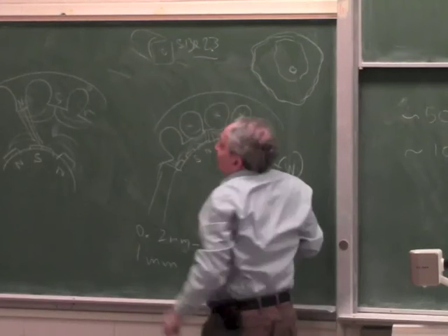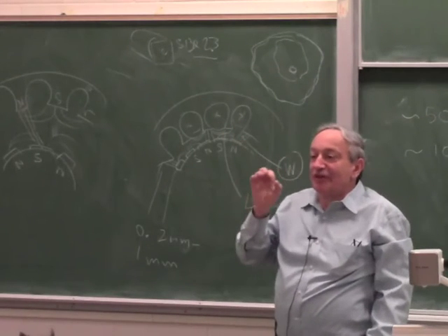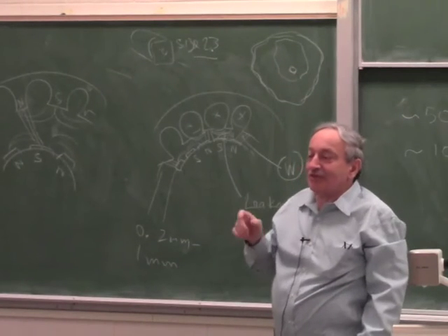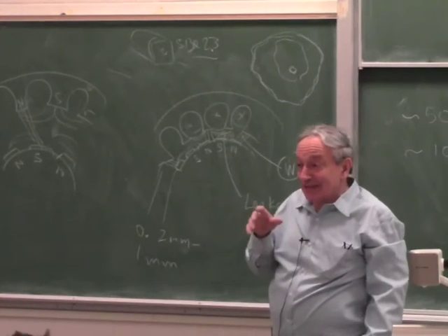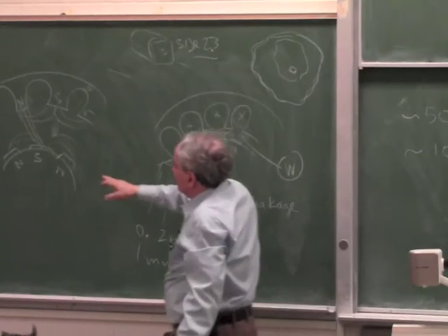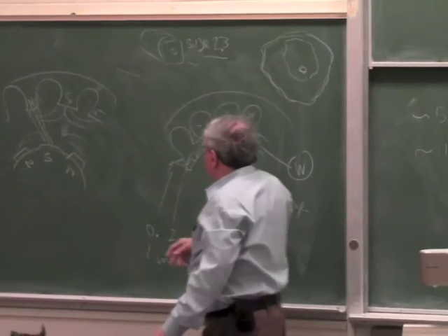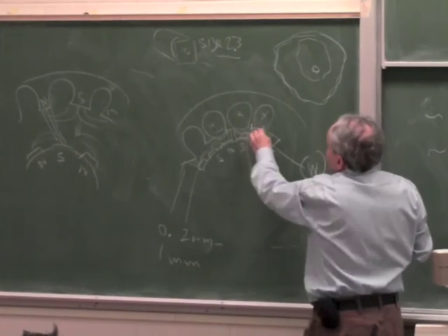So in this type of motor, the armature is only about 25 millimeter diameter, right? And you have to divide the 75 millimeter circumference by 100 because it's 50 pole pairs, right? So each pole is less than a millimeter. So even in a normal stepper motor, the gap is 0.2 millimeter, but the pole pitch is only 1 millimeter.